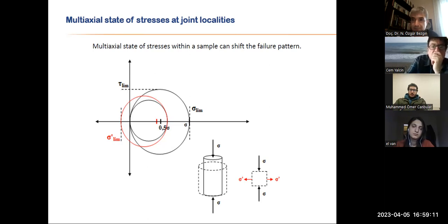So it's a beautiful thing. Structural design in this sense is a beautiful thing. By manipulating the way it responds, you can manifest a higher strength from that. For example, if we are talking about an axial compression stage, well, if it's unconfined, it will have one strength. If it's confined, it will have a different level of strength.